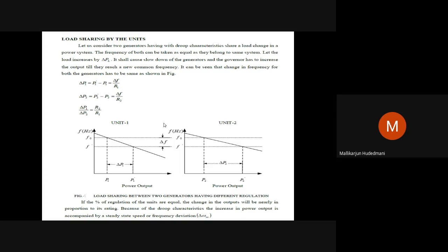Whatever it is, it becomes an issue with operation. Whatever generators we have, respective to their capacity and their droop, they are functioning and developing output for our requirement. We are concerned only with the generation aspect now. We are not looking at who is doing it. We are just operating. What is the current operating point? What is the shift in operating point if load occurs? How to correct it back is our interaction. For that, load sharing is the thinking.